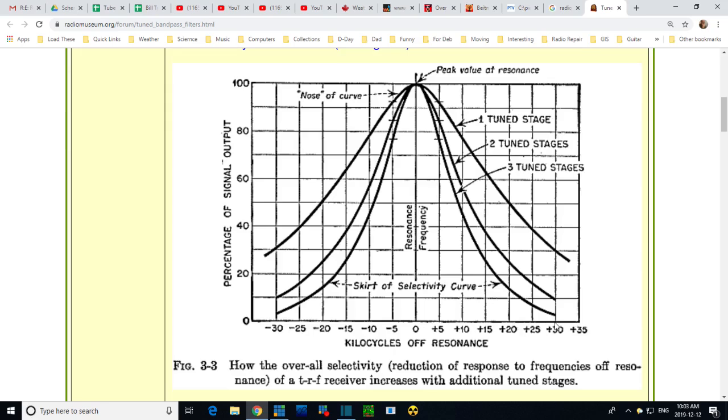How far away would 1050 be? Way off the chart here. And then on the other side of that, an equal distance away further, is that image signal. Wow, my gosh, this must be down to almost nothing. It must be way down by then. Of course, the curve here is kind of indicating that when you get down near the bottom here, you can go a long ways out and a little bit of signal still making it in.